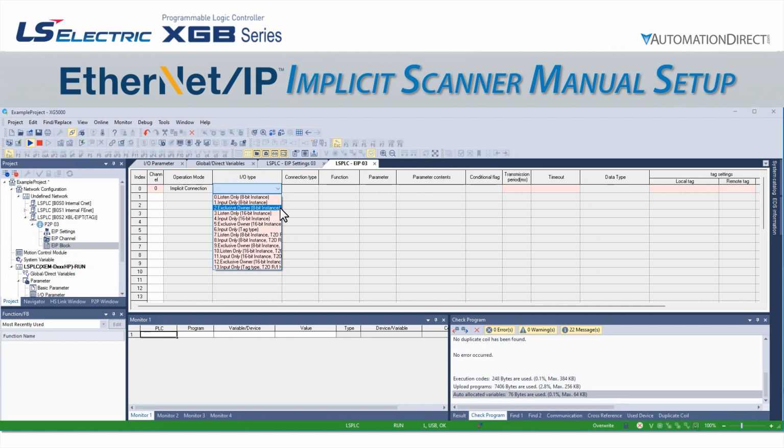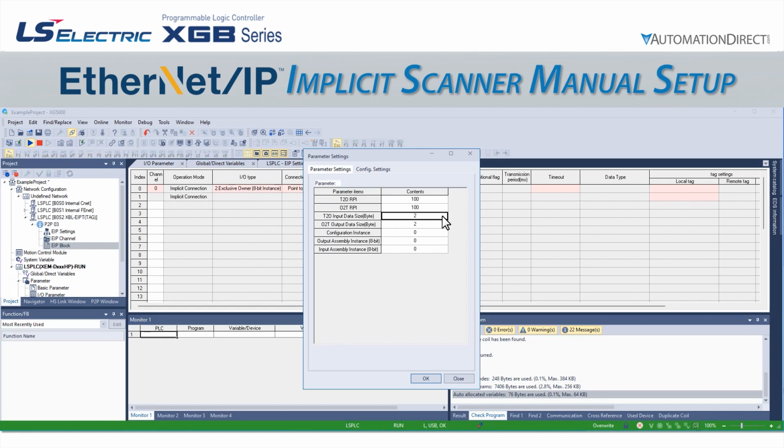Since we want to control the drive, not just monitor it, and the instance locations are below 255, we will be doing exclusive owner 8-bit instance. We will use point-to-point still, and when we select parameter, we will now have to set the T to O and O to T data sizes, config instance, and output/input assembly instances based on the adapter device documentation we looked up earlier. We will set the input message to be size 32 bytes, and the output message to be size 6 bytes. The input instance is 101, the output instance is 100, and the config instance is 102.